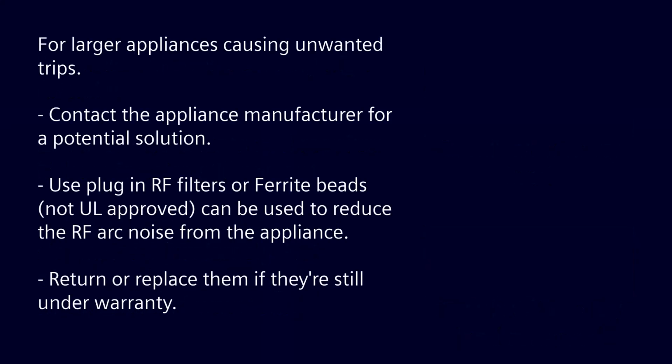If you have a larger load, such as a dryer or a microwave, you will have to reach out to the appliance manufacturer for a solution. You can also try using plug-in RF filters to reduce the amount of RF noise being emitted by the load. You can compare before and after using the Live Data or Record tab. In the next video, we'll go over how to troubleshoot ground faults.